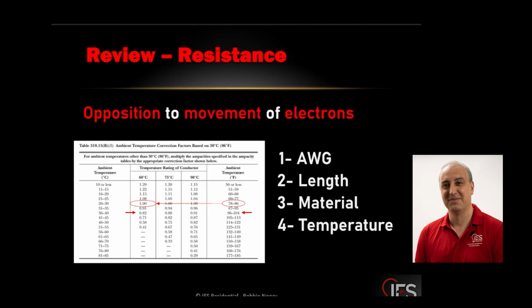So these are concepts that, as an electrician, you guys are new, you're just starting. So this is a primer for you to see what's to come. You'll learn about these down the road. But I want you to understand that all of this is because temperature increases resistance. So your 12 gauge copper wire that was rated for 20 amps in a hot environment at a chemical plant or an attic in Arizona is no longer considered 20 amps because its resistance jumped up.